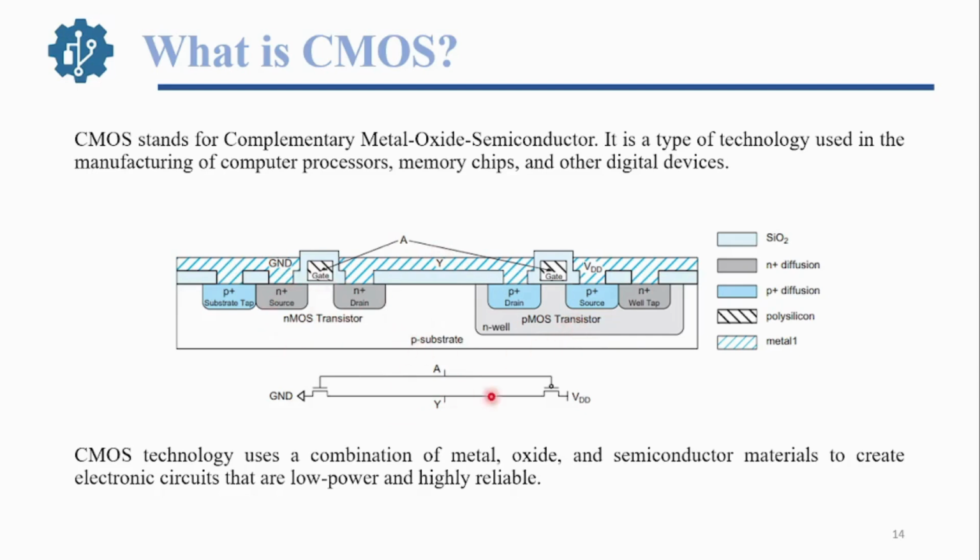Basically, you see here the complete substrate is P-type, and we create the N well for the PMOS transistor. Same as in the previous design, you saw here both sides of N plus doping for creating the NMOSFET, and P plus doping for the PMOSFET. We saw here in the single substrate, and the circuit diagram looks like this. You see here.